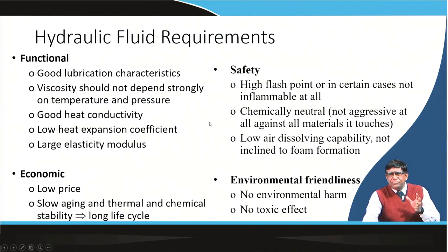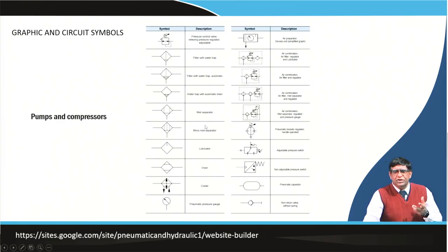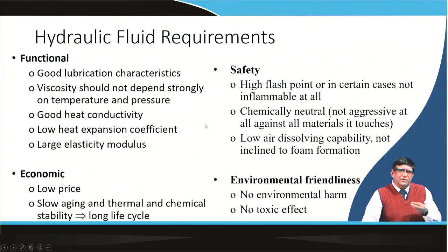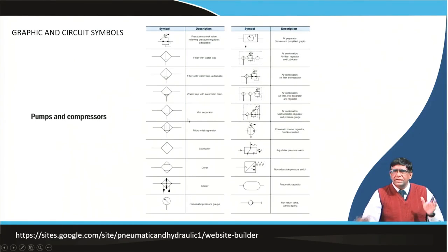These are some of the conditions on the basis of which hydraulic fluids are made, which are sometimes emulsions, oil in water emulsions or water in oil emulsions, and sometimes mineral fluids. Depending on the type of work, you may have additives to make it non-inflammable or corrosion resistant, all these things are done.